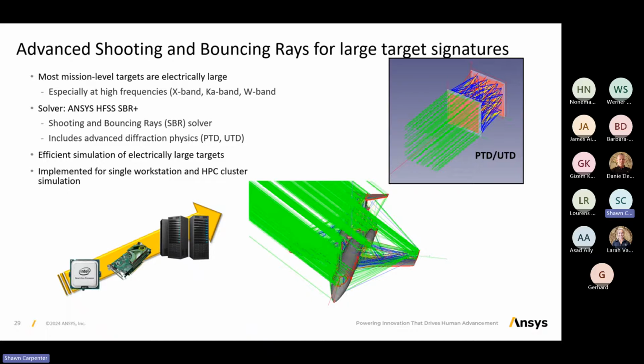So it really begins with a mesh of the body. And then when we look at what's observed in the far field domain or at a receive antenna, we'll re-radiate all of those current patches to the observation location using a Green's function wave behavior. So there's a real wave behavior involved in this. And that again, makes sure that we're accounting for all features of our target body as well as multi-bounce interaction that might take place.